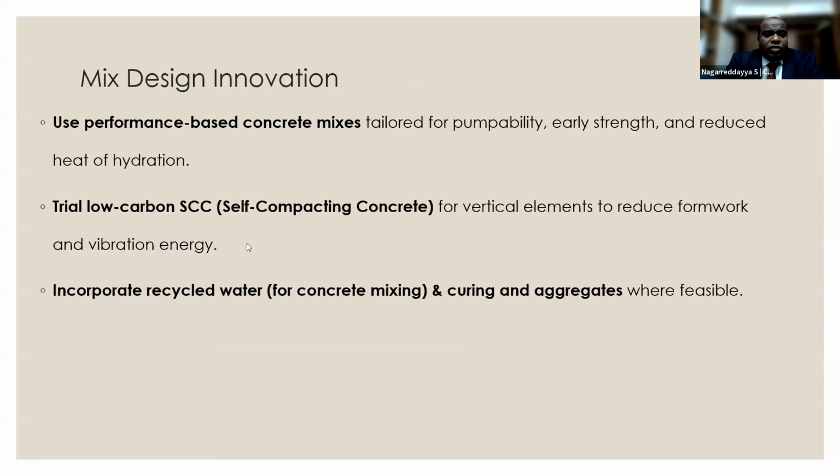So mix design innovation: use of performance-based concrete mixes, tailored for pumpability, early strength, and reduced heat of hydration. And trial low carbon SCC, self-compacting concrete, for vertical elements to reduce formwork and vibration energy. And incorporate recycled water for concrete mixing or curing, and recycled aggregates where feasible.